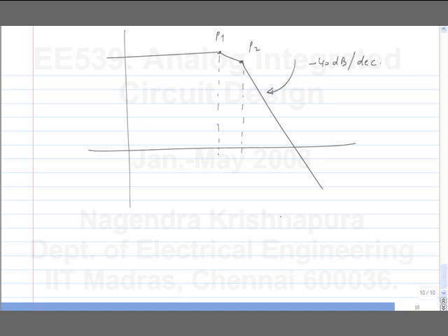So, one way is you introduce a further additional pole so that you get something like this. That is always possible, right? I can, in front of the entire amplifier, have another additional pole at a very low frequency so that these two will move beyond the unity gain frequency. So, this is something else I could do, but this is kind of inefficient.